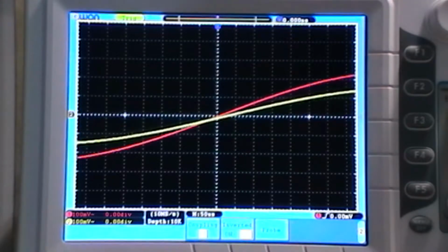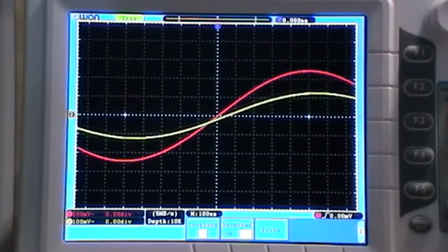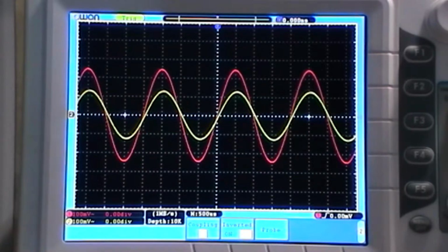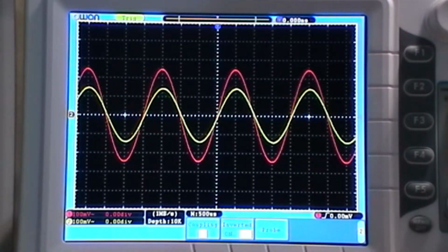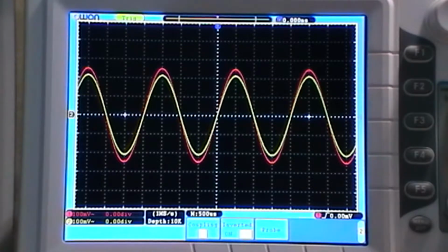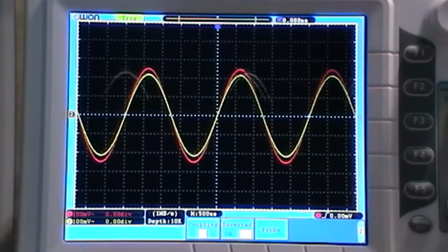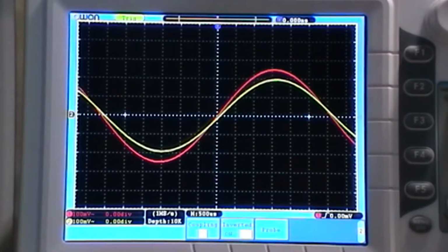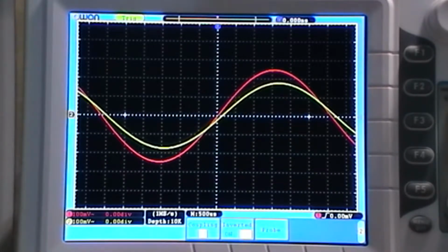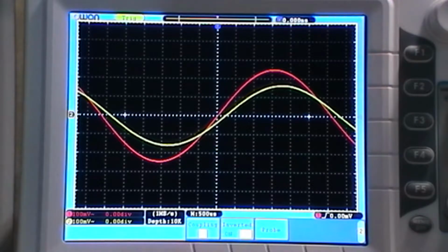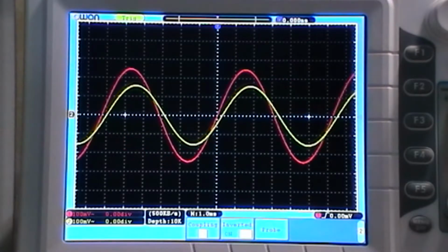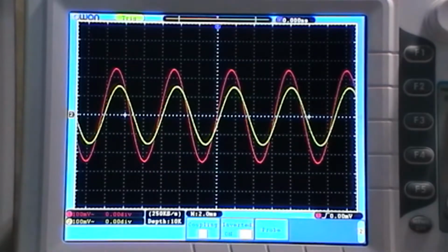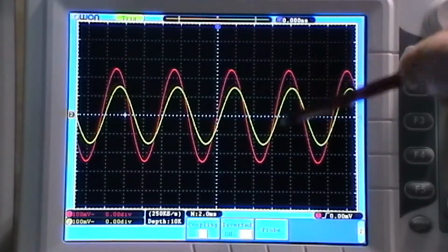So turn the signal on, and supposedly we're already attenuating this, because the cutoff point on this is, let me just turn it up, at 160 hertz. So I've got 159, 160, which is where the minus 3 dB should be about.